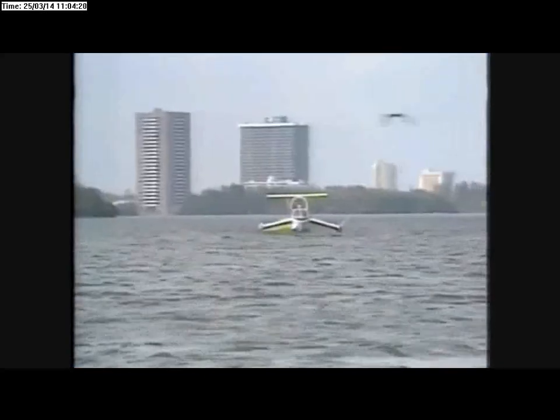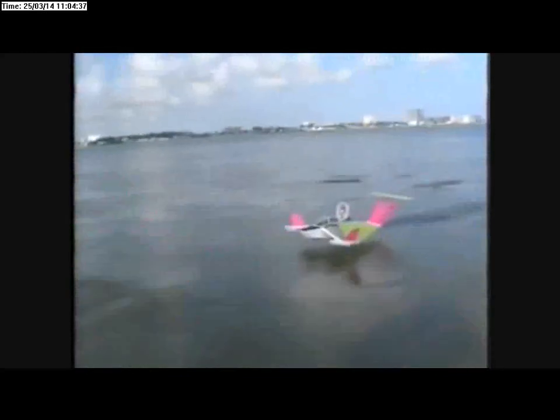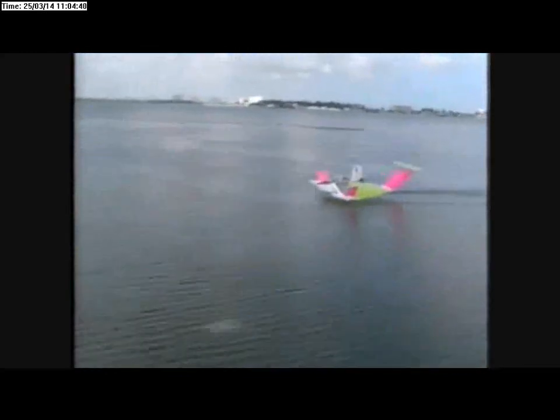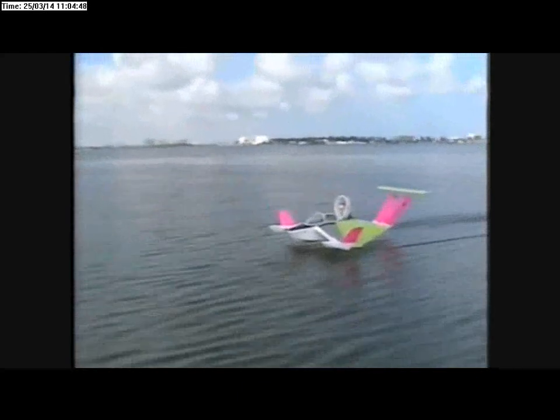Once it's in its flight mode, that's because the air pitch is a ground effect machine, something utilizing that well-known phenomenon. When a wing approaches the ground, it experiences increased lift and reduced drag. The air-efficient ducted fan provides forward propulsion, skipping the craft along on its sponsons like some new trimaran. But as it accelerates past 25 kilometers per hour, the ground effect creates lift, and at 65 kilometers per hour, it takes off. To make this happen, the flare wing deflects air downwards, which bounces from the surface of the water, and so keeps the craft flying.